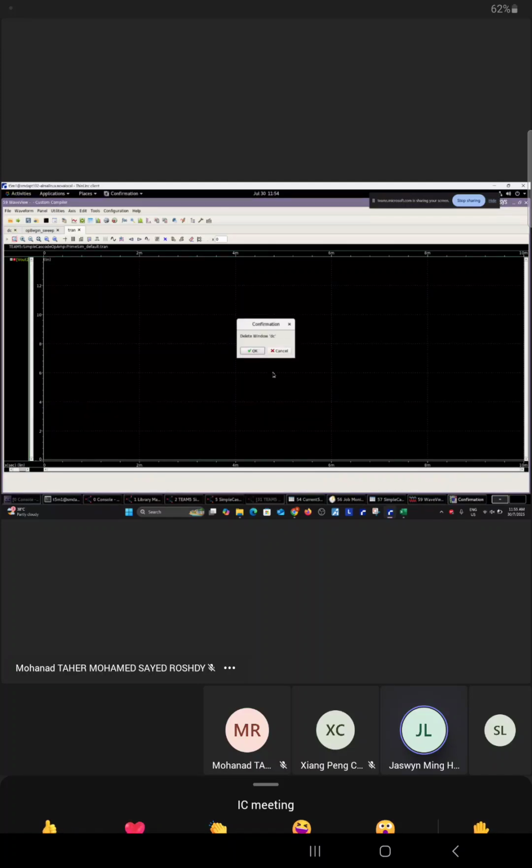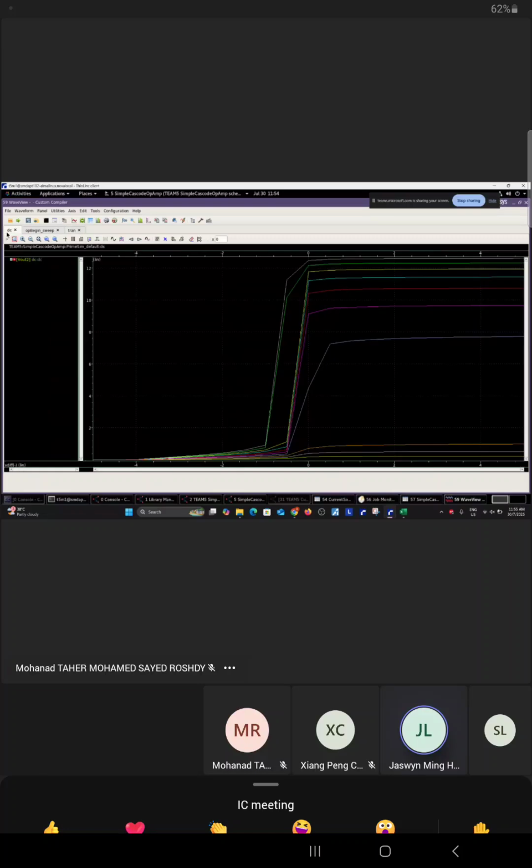You just see if you sweep the power supply, how it reacts, keeping everything else, for example, the VDIP constant. Then you see the power supply. You sweep it. What you can do later is you change the parametric sweep to VDD. Then you produce 10 different graphs of how the V out reacts to your VDIP. Now you have the V out against VDIP, right? Instead of 10 curves that correspond to different VN, WN, you change it so each graph corresponds to a different VDD.